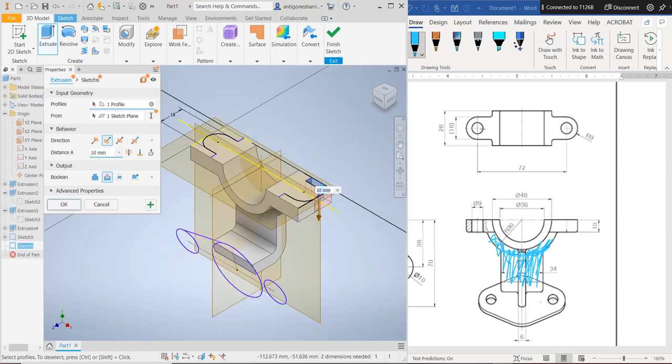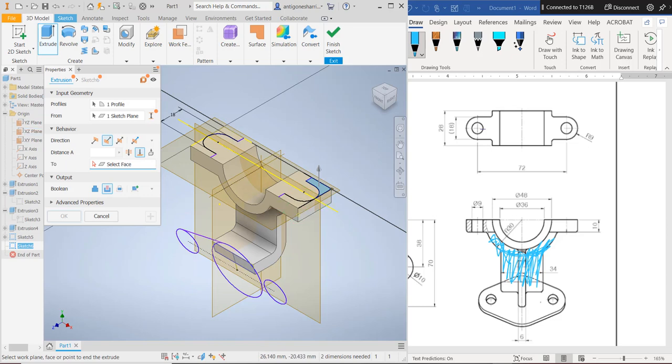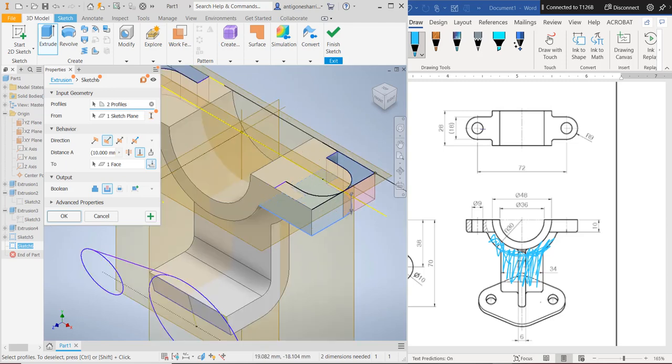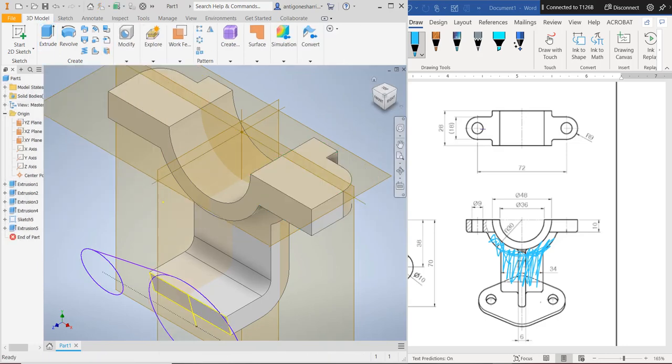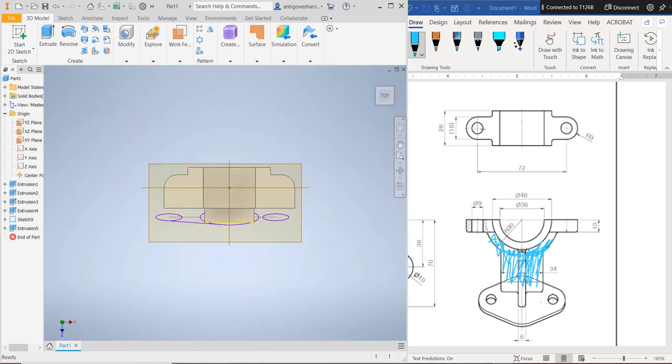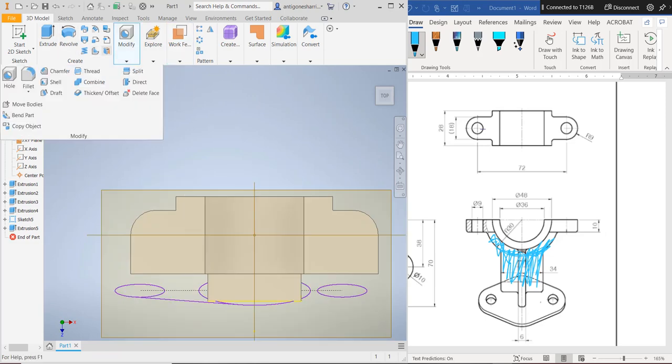Isn't that gorgeous? Of course, I'm going to say 2. Do not pick through all, trust me. Just don't, please. See that? I can't pick the front. Why won't the front work? Because I don't have a closed loop. I'm missing a line in front. But do you notice how I didn't, quote unquote, care? This is my way of showing you how mirror works.